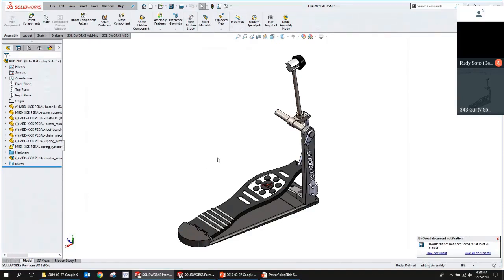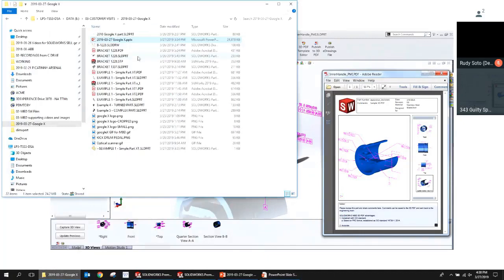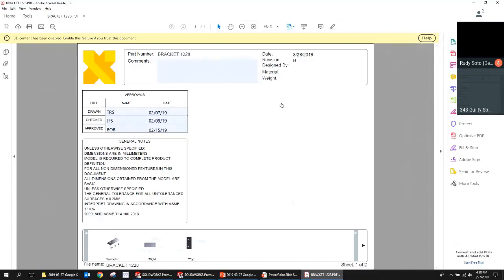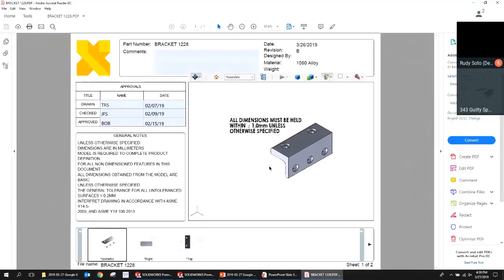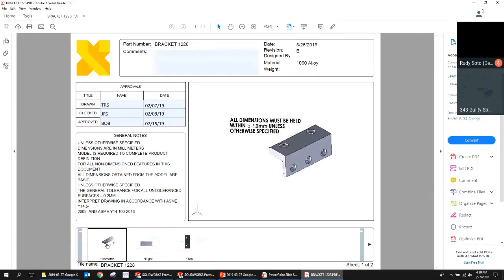So that's what a 3D PDF is, and what the SolidWorks MBD software does is it outputs to multiple frames in this 3D PDF format. So for example, I'll show you an example of a 3D PDF here that's been output from MBD. So this is just a simple bracket. You saw this when I was setting things up for the presentation. Earlier in the presentation, I showed a slide with this bracket on it. So the 3D views that we created can be included in this 3D PDF.